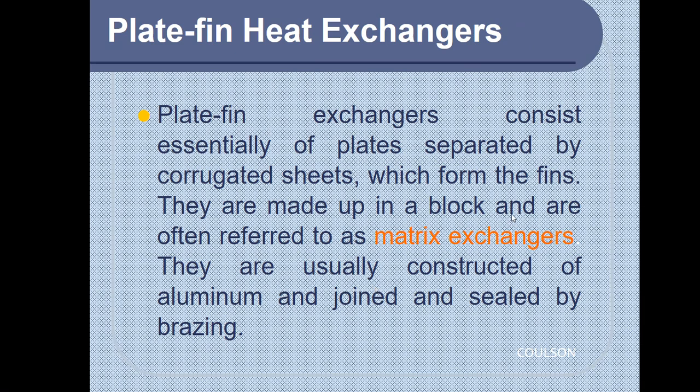It's actually the same as the plate and frame heat exchanger. The difference is that in between your plates you have corrugated sheets. The plates are separated by corrugated sheets, which may form what we call the fins.